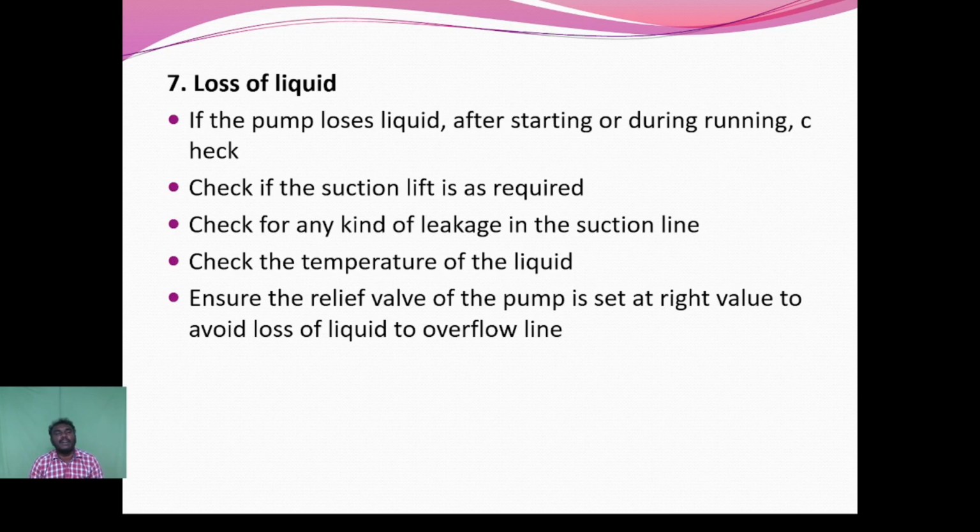If the pump loses liquid after starting or during running, we have to check these points. This is an almost important point: we have to set the suction lift properly. If it is below a certain level, severe damage will occur in the pipe.